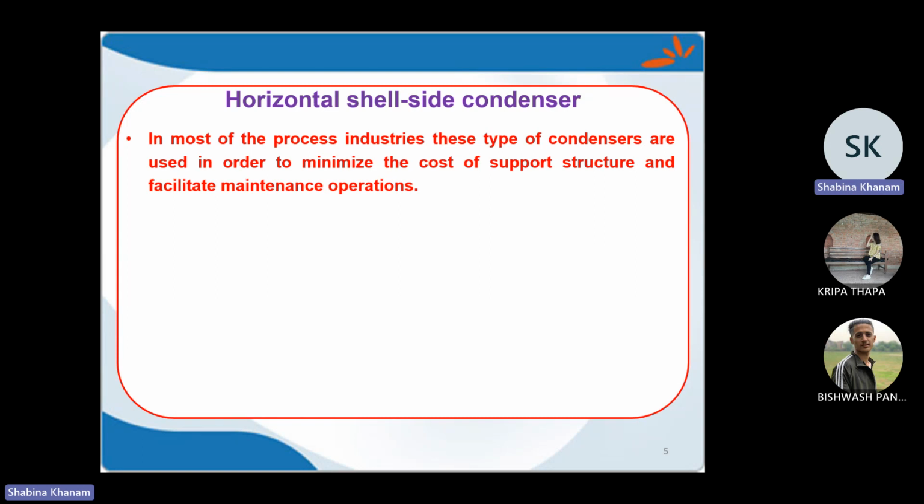Vertical way, if you remember, we have discussed in the last course, that design one, that vertical column, when we have tall vessel, for which support is very complicated and we need to design that very carefully. However, horizontal support, like saddle support, is not as complicated.